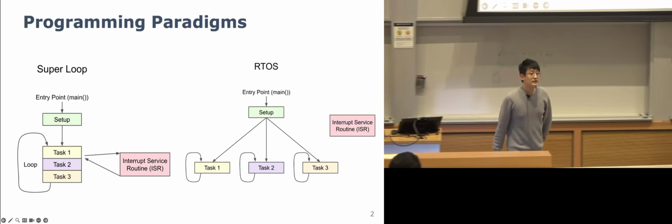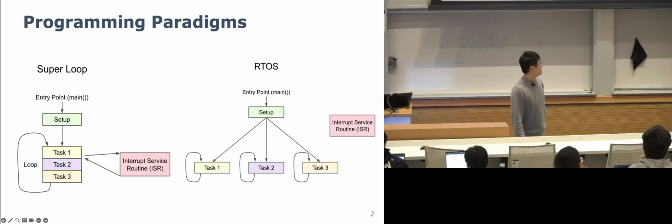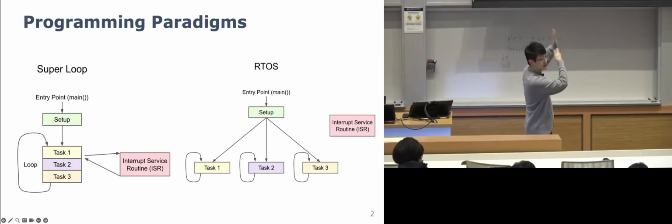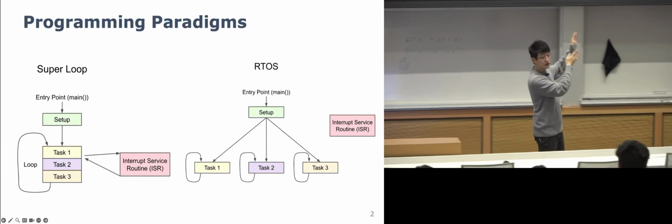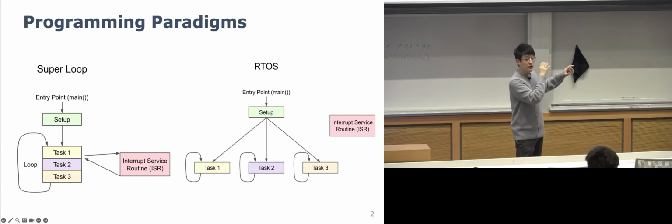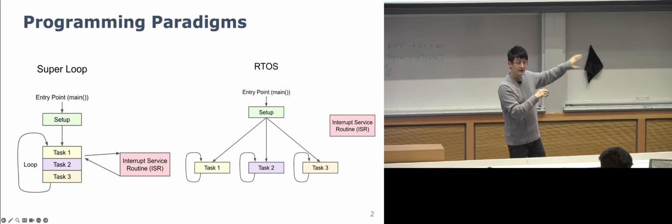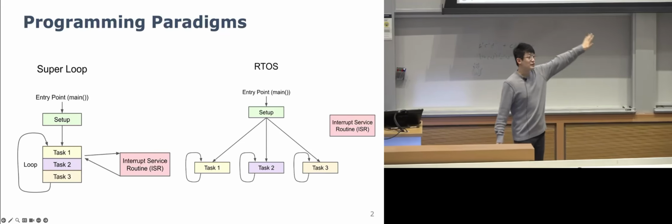In practice, do we have to implement this by ourselves, like the infinite loop? In practice, yes, you will need to implement it yourself. For the while loop, a lot of IDEs implement it for you. But if you work at a lower level, you do have to. And this one is a bit more complicated. You not only need each of the pieces of code, you also have to figure out how much space each task needs and assign it so that they don't overflow or invade each other.